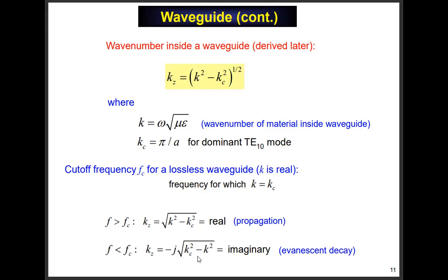And it's like the critical angle effect. You might say to yourself, what the heck? There's no loss. This could be a perfectly lossless waveguide, and the wave is attenuating? It's got an alpha? Why? It's like the critical angle effect. It's what we call evanescence. You can have a wave that decays exponentially even though there's no loss. That's possible. It's called evanescence.